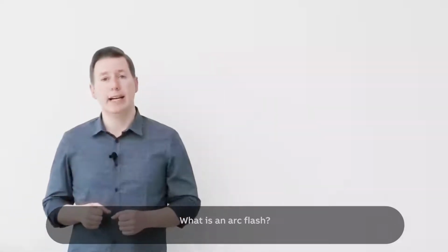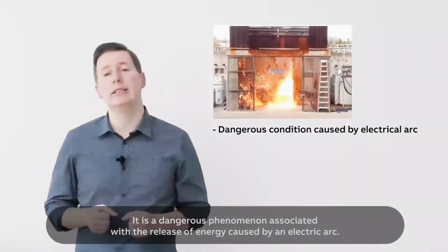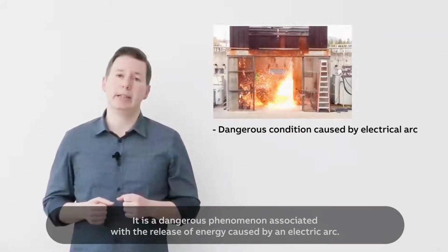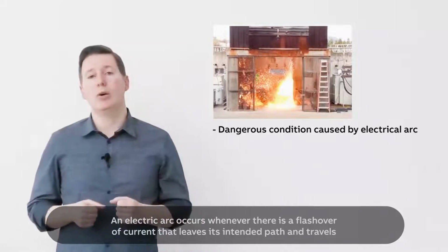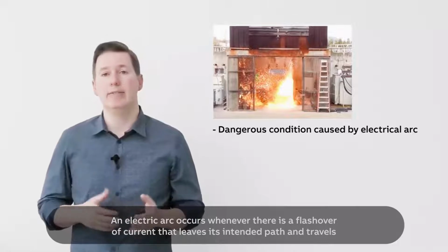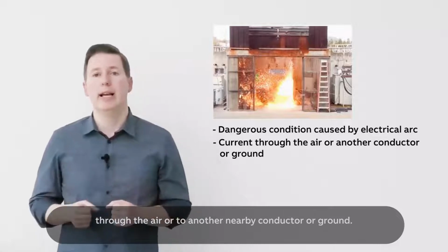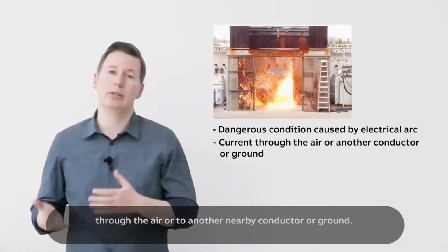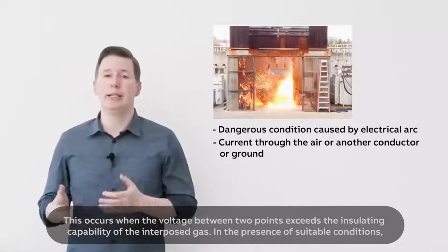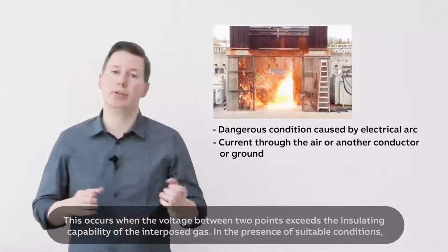So, what is an arc flash? It is a dangerous phenomenon associated with the release of energy caused by an electric arc. An electric arc occurs whenever there is a flashover of current that leaves its intended path and travels through the air to another nearby conductor or ground. This occurs when the voltage between 2 points exceeds the insulating capability of the interposed gas.